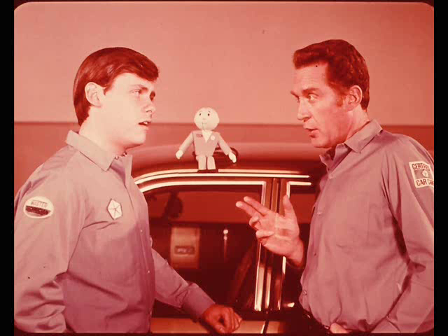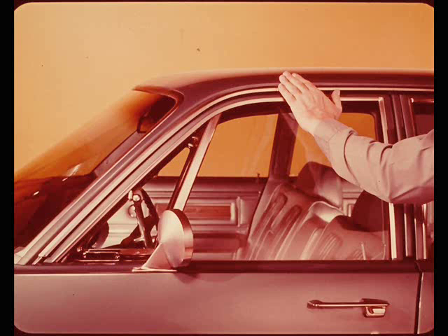What's the reason for the battery charger? Are you afraid the test will run the battery down? Well, not exactly, but you want the blower to build up the highest possible pressure inside the car, so you keep line voltage up with a charger when the alternator isn't operating. Well, that makes sense. Okay, how do you check for air leaks?